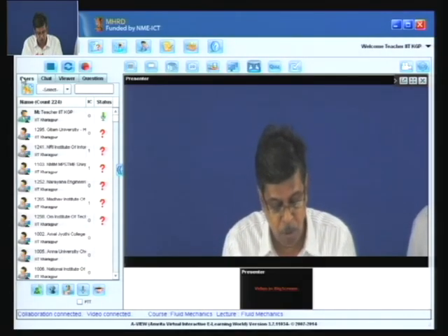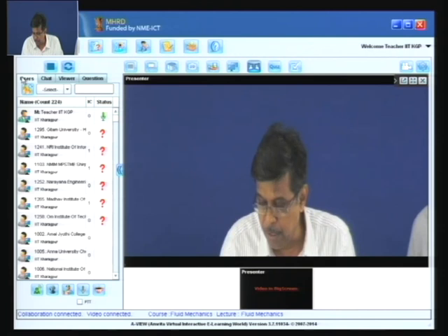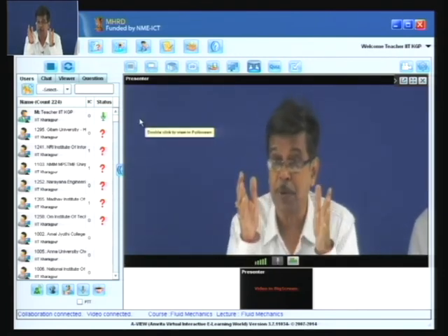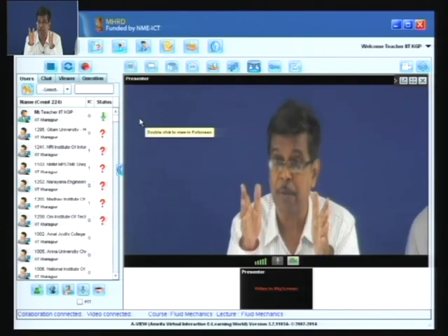You please go through your textbooks, but I tell you that this Reynolds transport theorem is very important in fluid mechanics. Everywhere when you write the conservation equation, we always write it with respect to a control volume, and there we write the statement known as the momentum theorem, which is nothing but the conservation of momentum, whether linear or angular, with respect to a control volume, where we always invoke the Reynolds transport theorem.